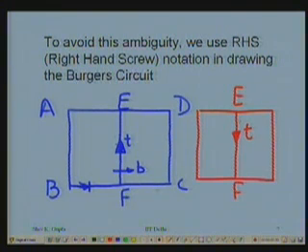Anti-clockwise. On the front plane you are drawing, and what will be the Burgers vector? Opposite to this, from P to Q instead of Q to P. I say whether you have chosen the direction of the dislocation line F to E or E to F, you have got the consistent result.